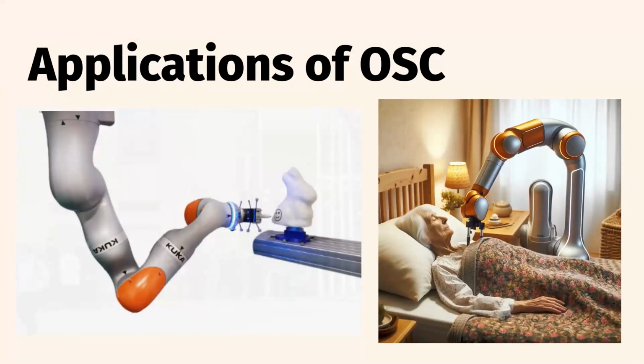Typically, large robotic arms are capable of moving very fast and have very high inertia, which means they carry a lot of energy when they move. That's bad if you're trying to interact with the environment because they're capable of applying really large forces that you might not intend. Operational space control allows us to more effectively control the force our robot applies to the environment, which will be particularly useful for delicate operations or, in our case, drawing on a surface.